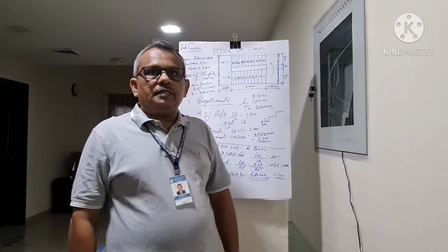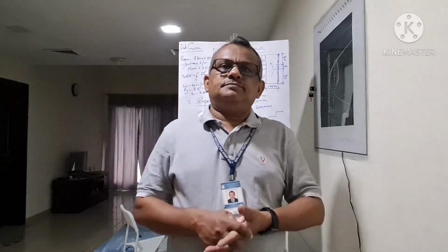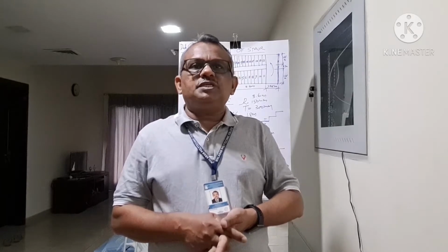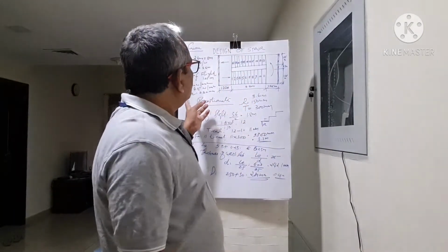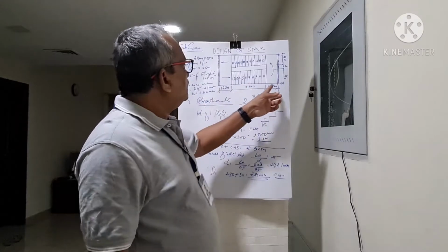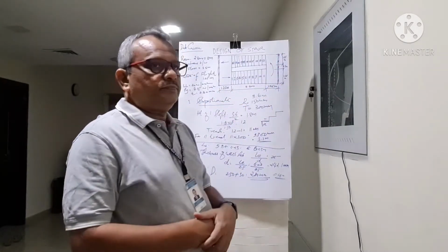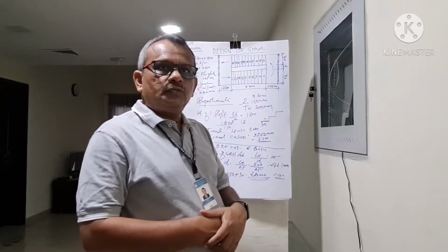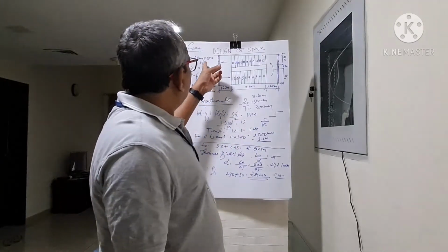For that, first of all, the first step is to proportion the stair. That means the number of steps to be designed. For that, from the given criteria, to proportion, the room size is given. It is 5.8 meter, this one 2.8 meter. The two measurements of the room. Now, the vertical distance between the floors is given as 3.6 meters.